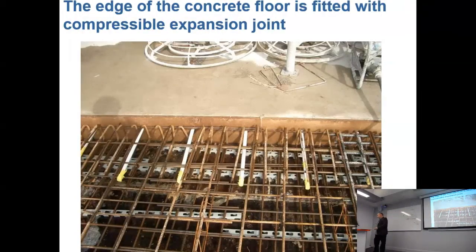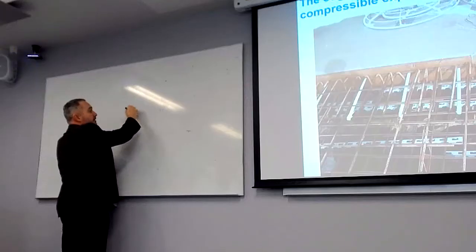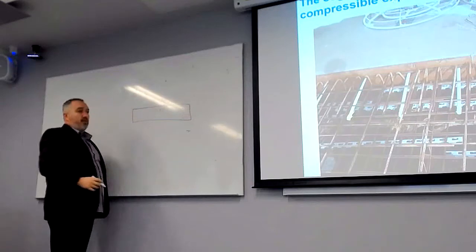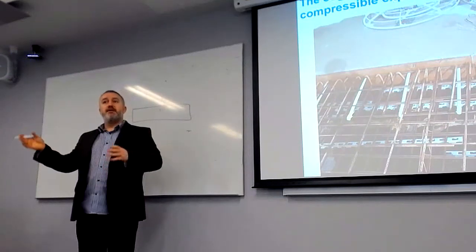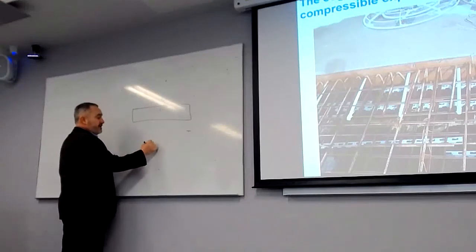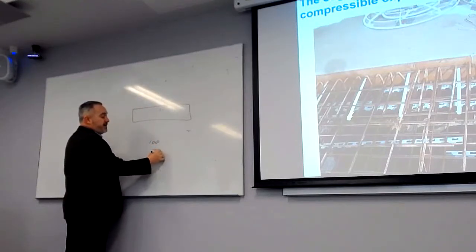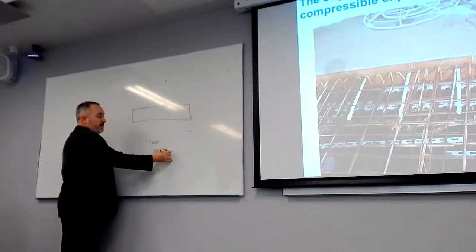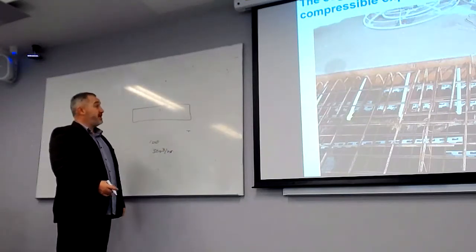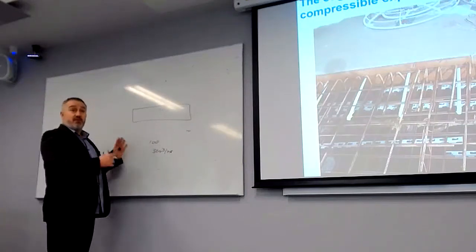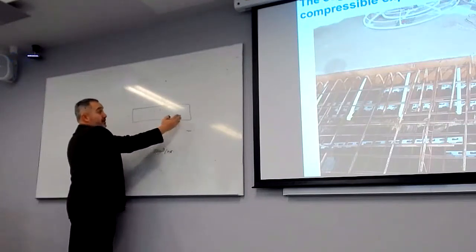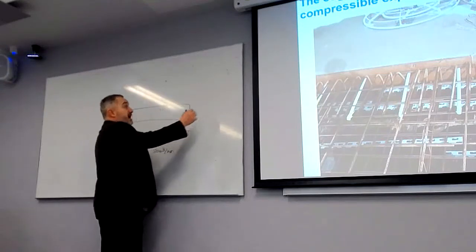Concrete. We could pour it at 100 meters cubed per hour. Just keep on pouring it and pouring it and pouring it. But what you'll find, due to waiting for concrete trucks to arrive, they get stuck in the traffic, instead of 100, you tend to get roundabout 30 meters cubed per hour. You could be waiting for the crane, if that's how it's delivering the concrete. And so at some point you have to stop your slab, and then the next day cast your next slab.